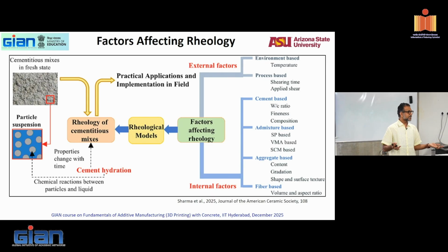If you have aggregates, it becomes a completely different story. Shape of the aggregate, size of the aggregate, volume fraction of aggregates, all of those affect the rheology. With aggregates, the paste will coat the aggregates as a coating around them. Then the paste thickness around the aggregates or total paste volume also starts to influence workability. So you can start to think about all the different kinds of things. In our discussion, we'll try to keep it simple to understand what the basic processes are, but make sure that all these factors are equally critical.